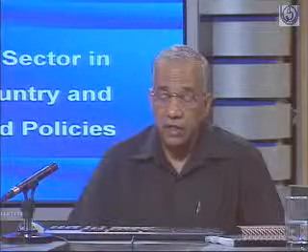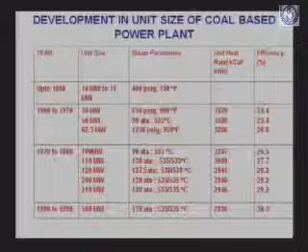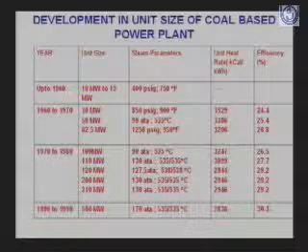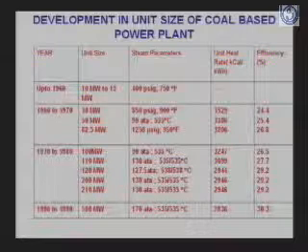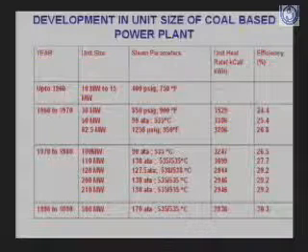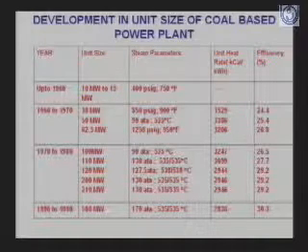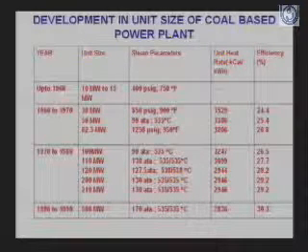So this is a high efficiency cycle, and you see the heat rate number comes to 3099 kilocalories per unit, which amounts to around 27.7% efficiency. So once we adopt from 90 kg pressure to 130 kg pressure, the efficiency has increased from 26.5 to 27.7%.